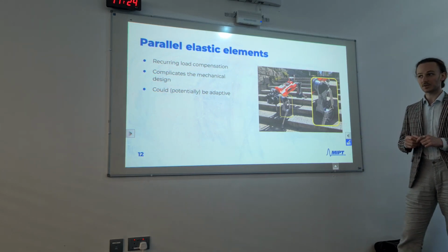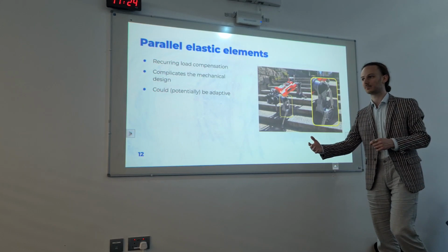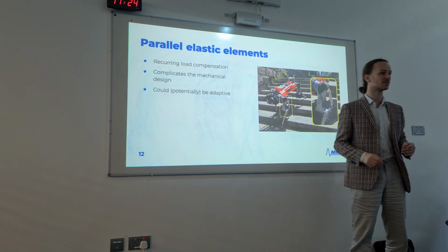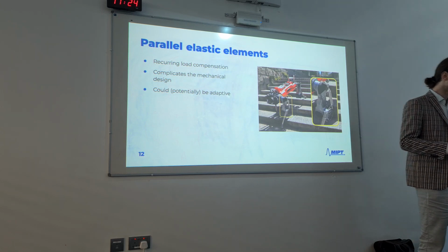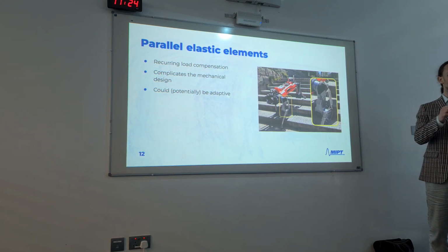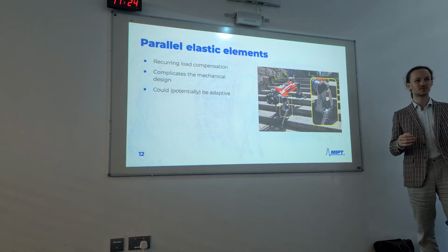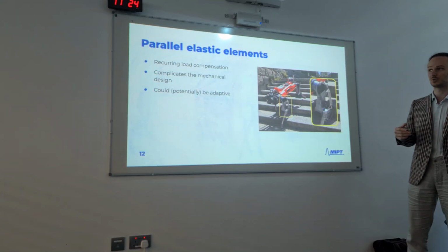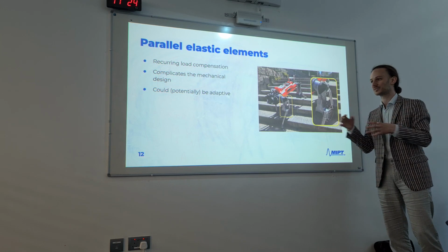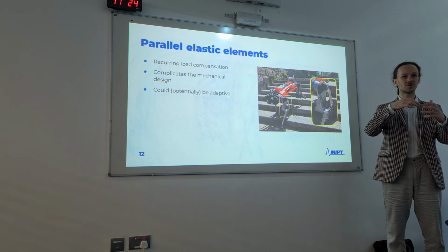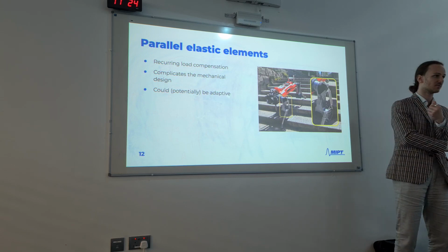And another cool thing, and a perspective topic of research, is to make the springs adaptive. Actually, we can change the stiffness and the zero position of springs with some small servomotors that will rearrange the spring inside the arm, the leg.